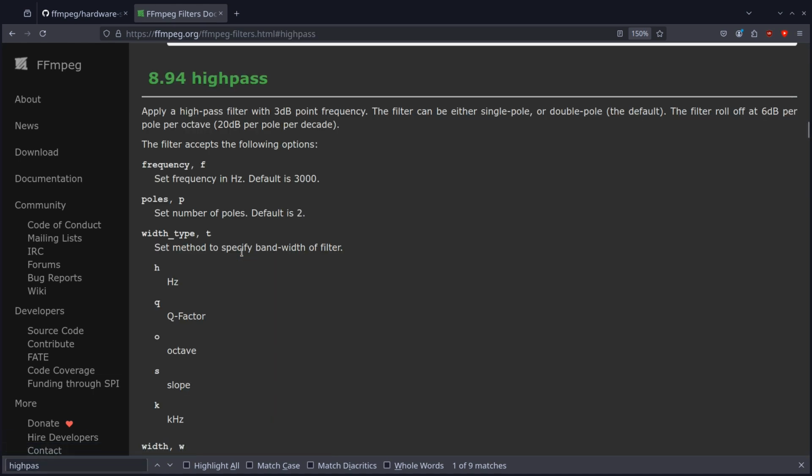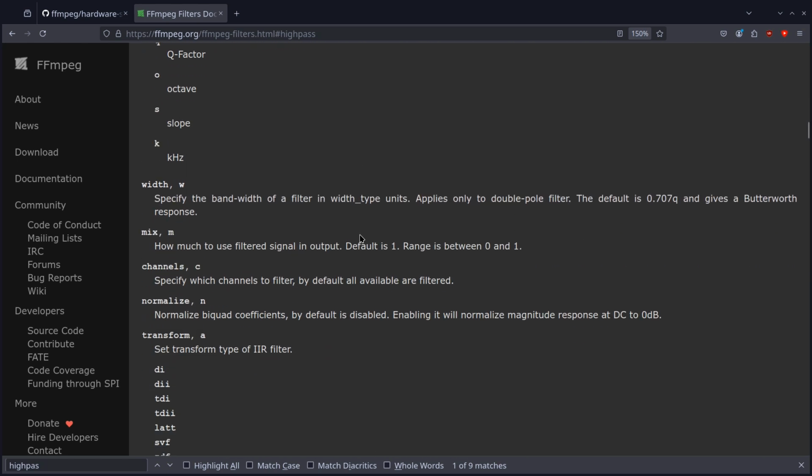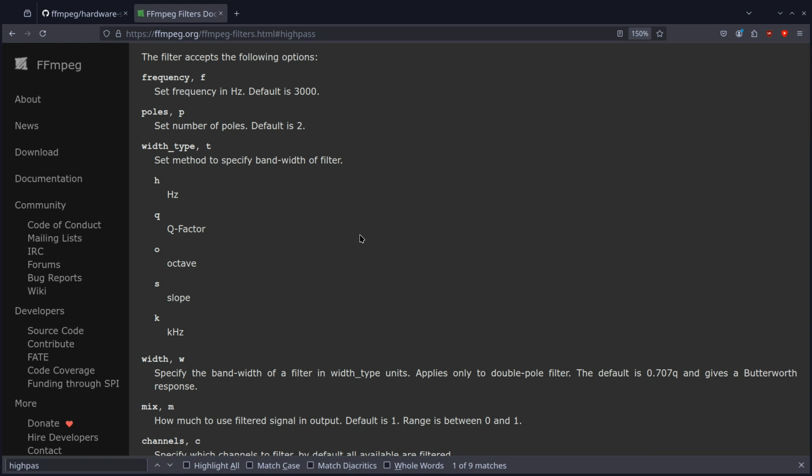These are actually two different filters, but I just put them together because everybody in audio kind of knows what's happening with the high pass, low pass. Basically, it's just cutting off. A high pass just tries to cut off the lower frequencies and lets all the high stuff pass. So imagine you have a lot of low rumbling sounds, maybe air conditioning units or cars driving by outside that are like in the 50 hertz range or 60 or 80, even up to 100 hertz, but maybe not 100, maybe like 80. And you want to roll those low frequencies off. You would use a high pass filter.